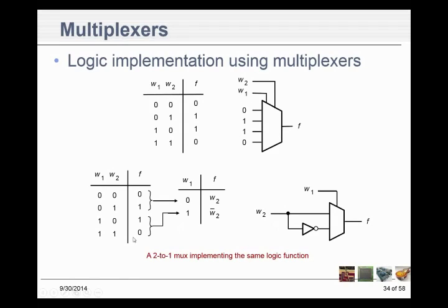For this one, this is what we want. But this is what we have for W2. It's inverted. So we tie an inverter there. Okay. What if it was 1, 1 that we needed there? What if this was an OR gate, not an exclusive OR gate? All we'd have to do, we wouldn't have to tie this to anything except for a high up to the supply voltage. Okay, and we would still have a 2-input multiplexer that would be working as a 4-input multiplexer.